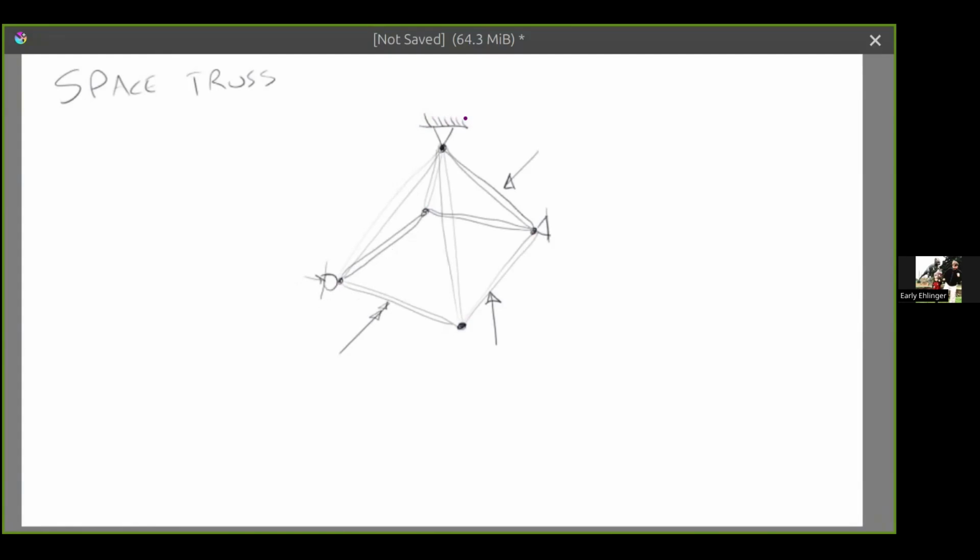That becomes the differentiating factor that makes something a space frame instead of a space truss. Obviously, the more degrees of freedom and complexity you allow, the more complicated the analysis becomes as you progress through these 6 types of structures.